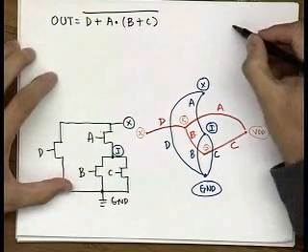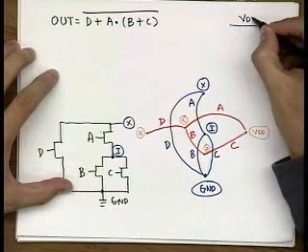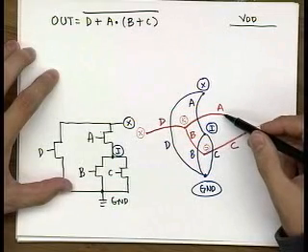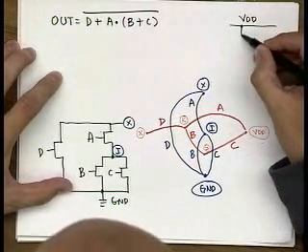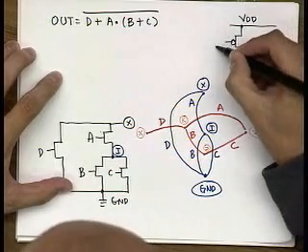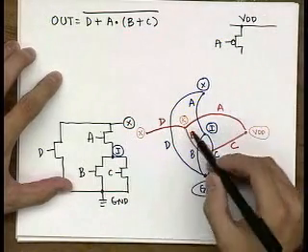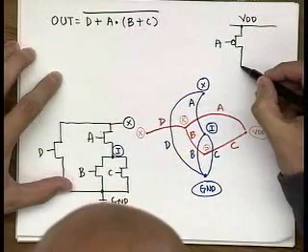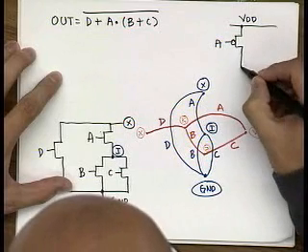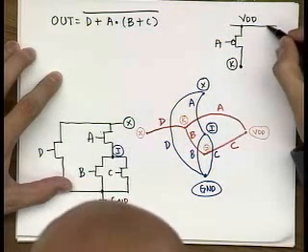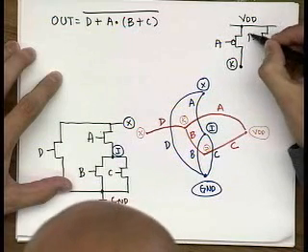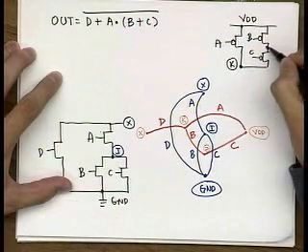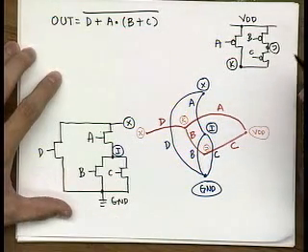Okay. And now using this graph, I can reconstruct my pull-up network. So here's my VDD over here. And then I know that I have PMOS transistors basically here. So I have a parallel combination of A, and then I have a serial combination of B and C. So this now goes to node K. And now this is my node J, that's the intermediate node.